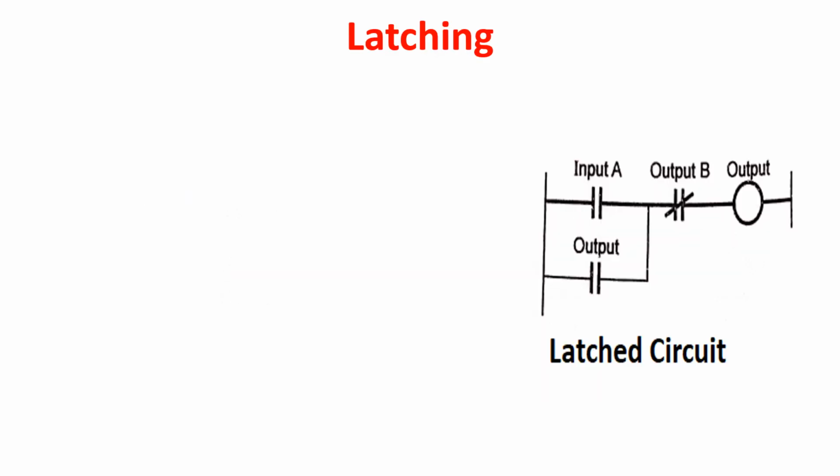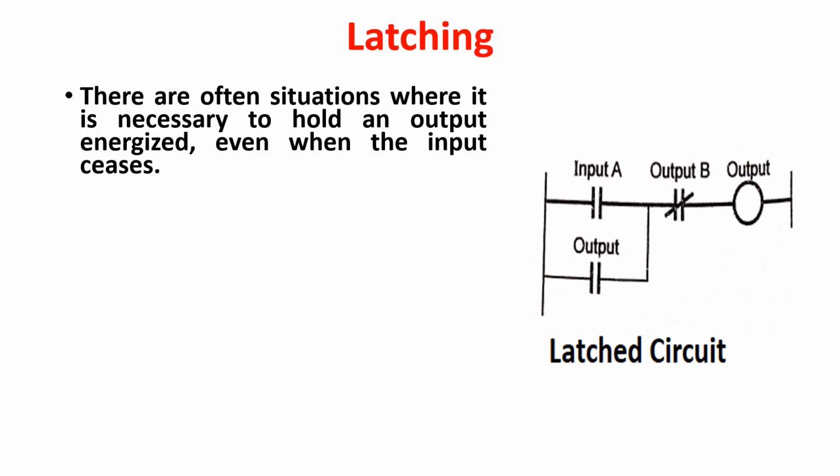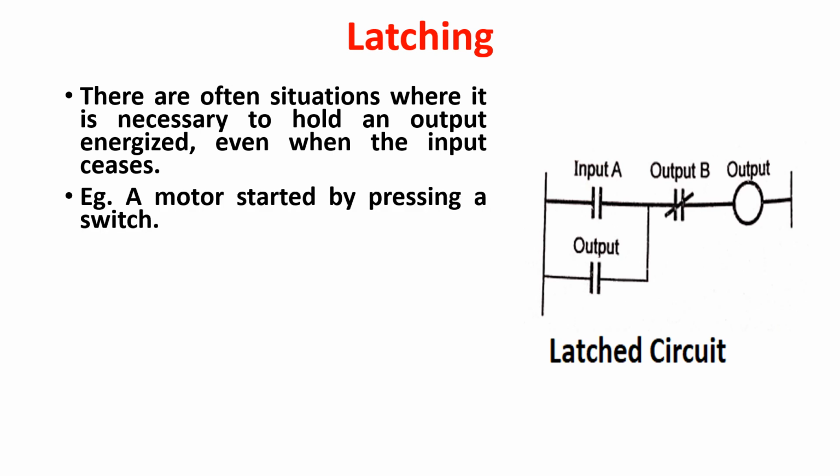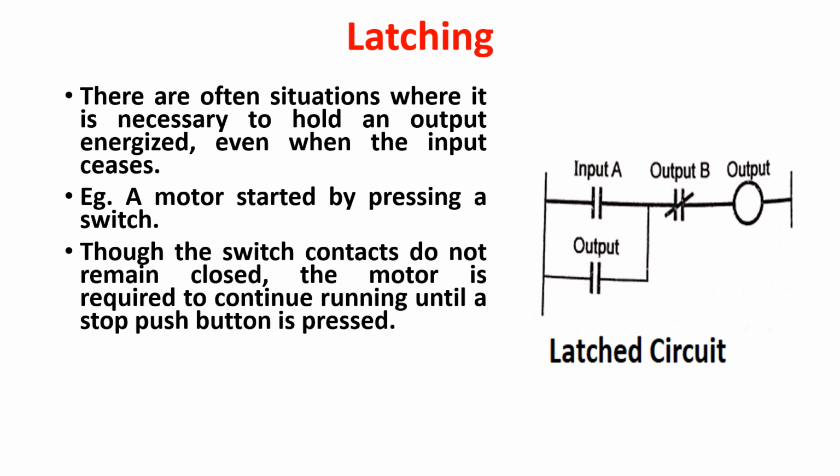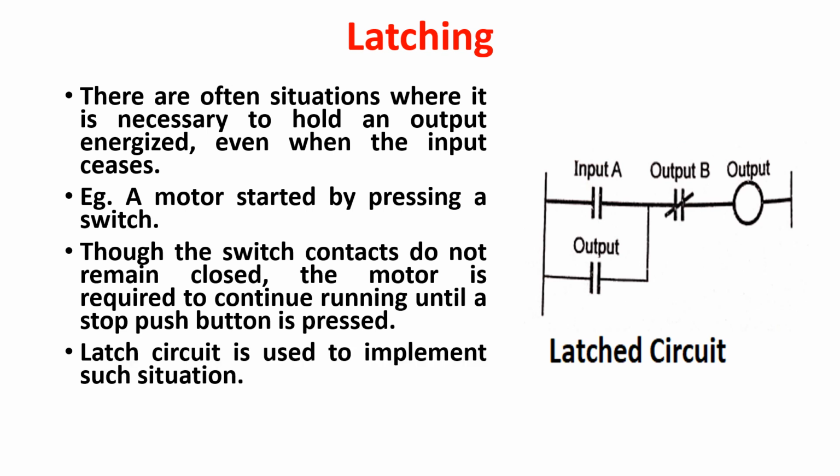Latching. There are often situations where it is necessary to hold an output energized even when the input ceases. Example, a motor started by pressing a switch. Though the switch contacts do not remain closed, the motor is required to continue running until a stop push button is pressed. A latch circuit is used to implement such a situation. The figure shows the latched circuit.